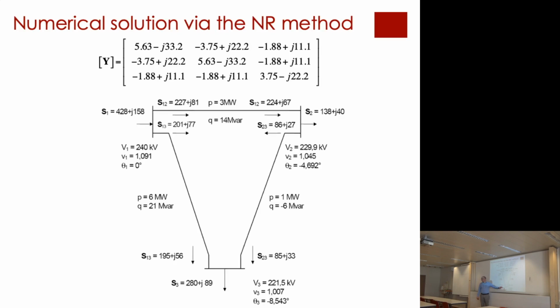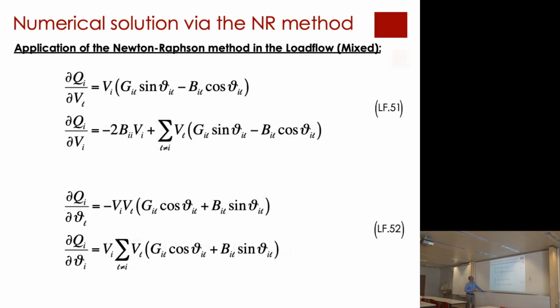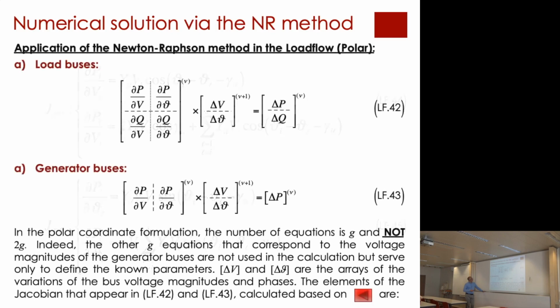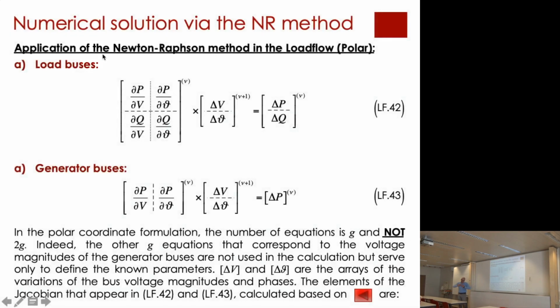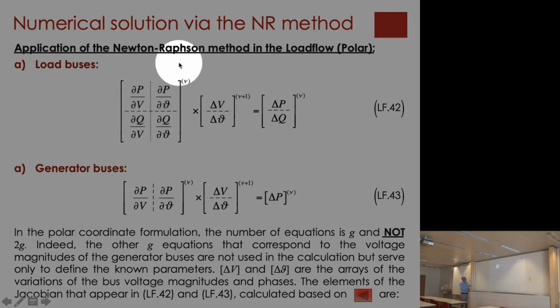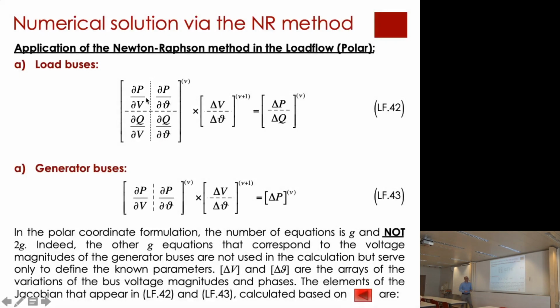You need to compute the partial derivative of the voltage at this bus with respect to the injections, right? Do you have this quantity? Yes, you do. If you go back, you see? You have the dP over dV, which is the inverse of this quantity. You have the dQ over dV. So if you invert this Jacobian, you get the dV over dQ and dV over dP. So essentially you get the sensitivity of all the voltages as a function of all the injections.